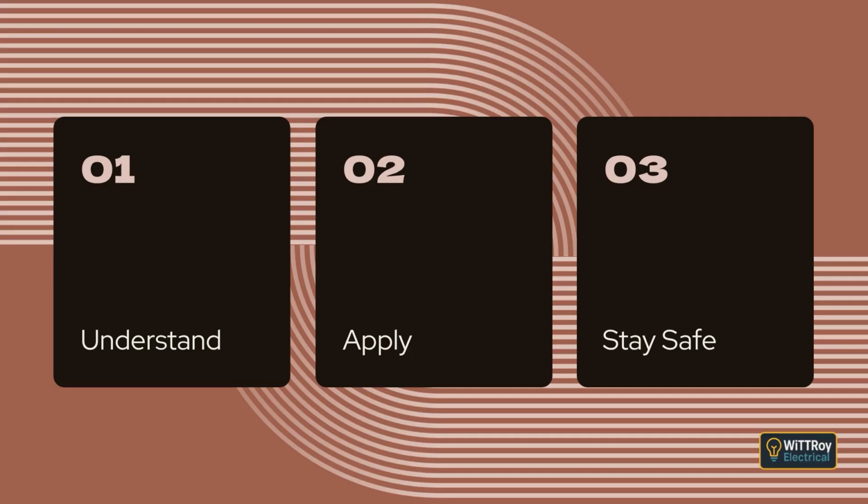Clause 3.9.8.2 Different electrical installations. Conductors belonging to different electrical installations must not be installed in the same wiring enclosure unless proper segregation is provided. Where different installations terminate in a common enclosure, they must be effectively segregated. This may be achieved by using sheathed cables, barriers, or by spacing.